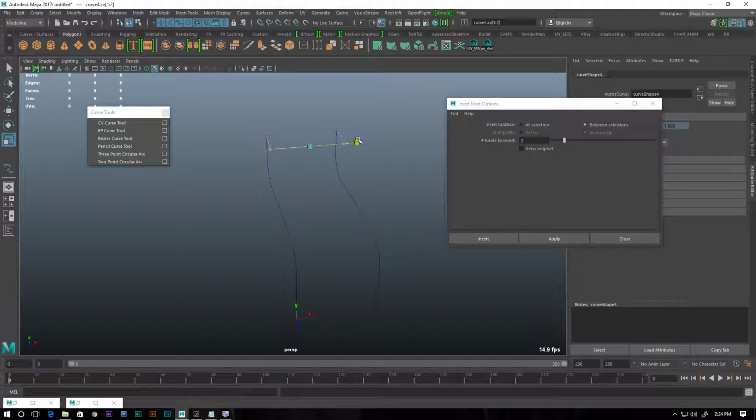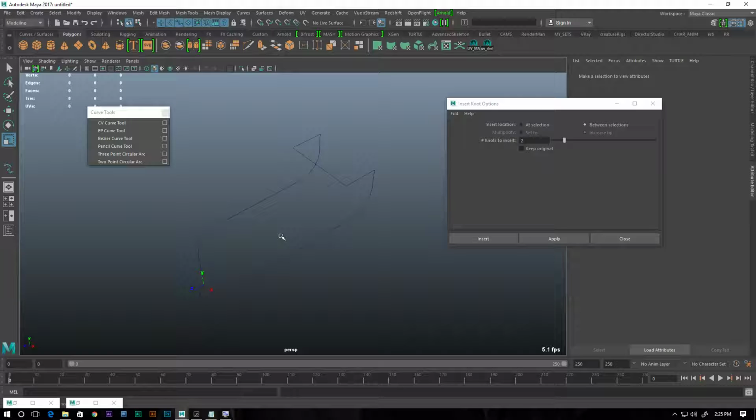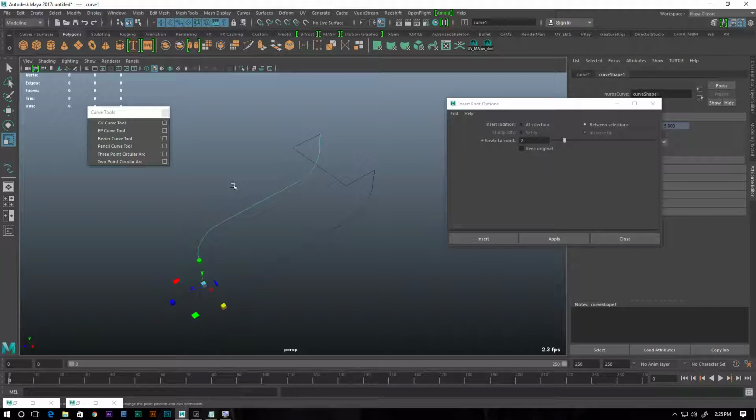Watch closely. So it's quite cool. Now I have 4 curves, and I'm going to use a bi-rail tool. So we have 2 rail curves. These are like rails for the train or something, and this is the profile which is going to be extruded along these 2 rails.